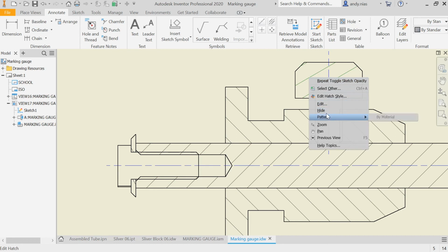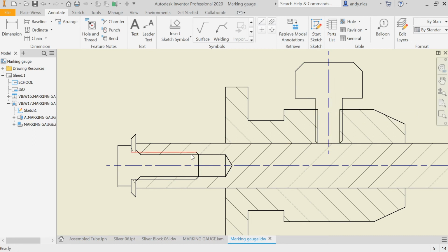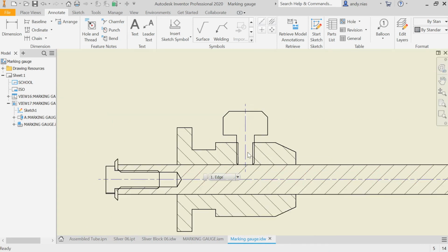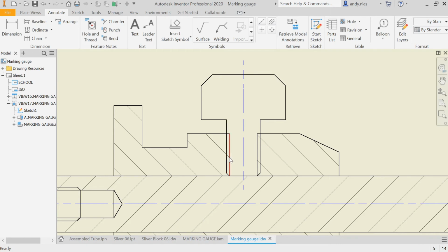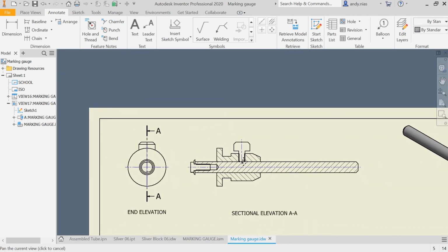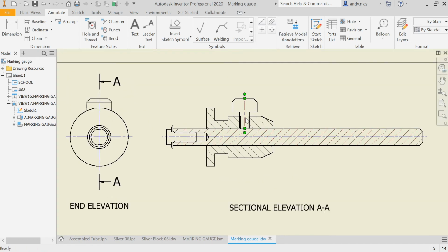Doesn't really solve it. If you really needed to fiddle it, you'd have to open this drawing in say DraftSight or another editing package and mess around with the lines so that it actually comes out right. You could move that one back, for example. Just a note to remember that it isn't actually correct, but it's the best we've got.